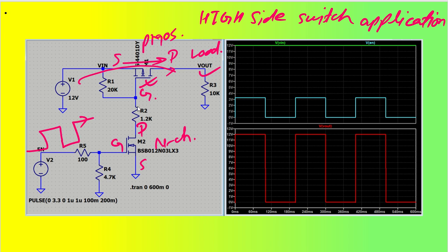So hope you have a good understanding of how to switch on this particular input to output. One more thing you can see many circuit designers doing is, instead of using a MOSFET, they use transistors. An NPN transistor can also be used to do this job at the low power switching here. Here a very low current carrying capacity MOSFET or transistor can be utilized, and here we will have to use a MOSFET with a bit higher current carrying capacity. We have to understand how much load it is consuming, or what is the current rating needed to drive the load. In that way we will mainly be utilizing a little higher power MOSFETs.